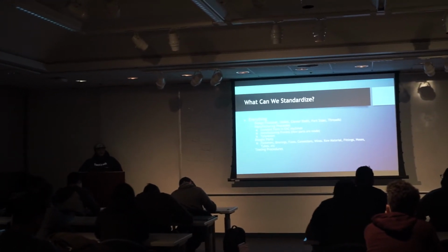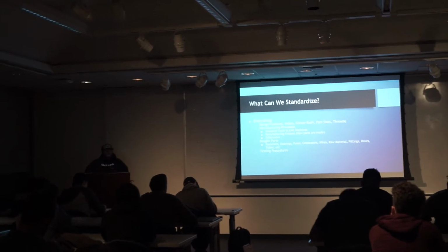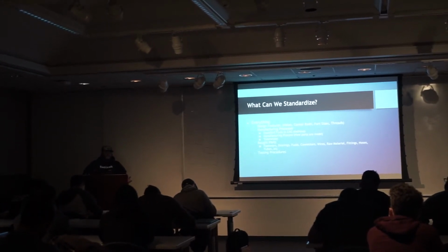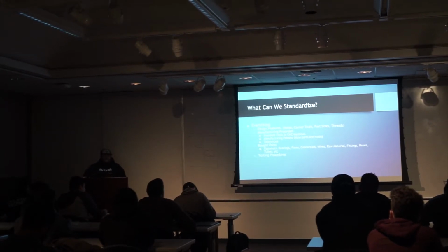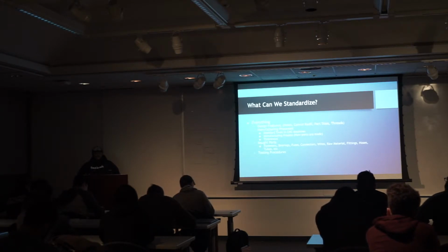Part sizes. I'm sure you guys are all familiar with raw material coming in certain sizes, right? You get an inch, you get an inch and a quarter. So if you take that into account when designing something, you can save material or make it fit something you already have or that you stock. And when you cut threads, if you're going to do standard bolts, 1/4-20, that means whoever's making it only has to have a tap, or however you're threading it, for 1/4-20. They don't need to stock every single thread size that has ever existed.